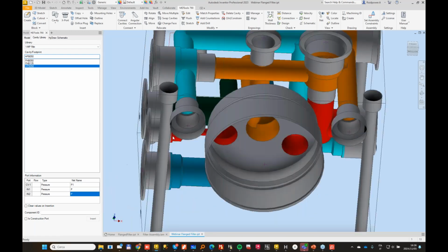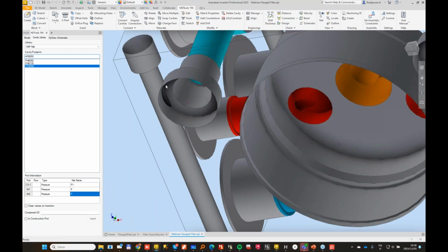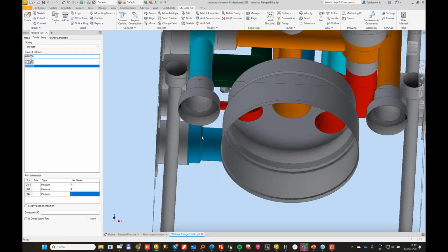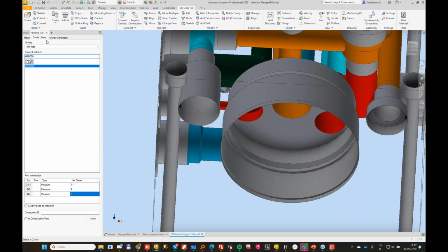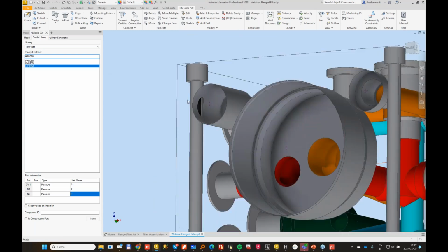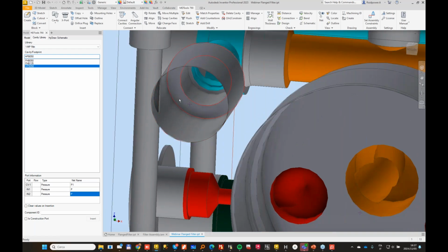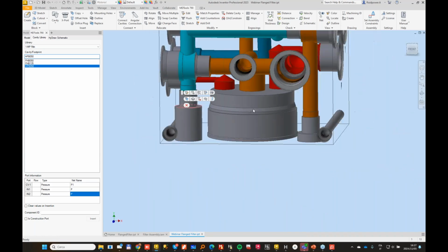What I can see here is I have the spot face of the plug entering inside the bolt holes. So in this situation, a technique that you could adopt is to really sink the plug. Let me make it 25 millimeters. So in this case, although you have 2 cavities interfering, the seal surface will be this, so there is no issue at all.